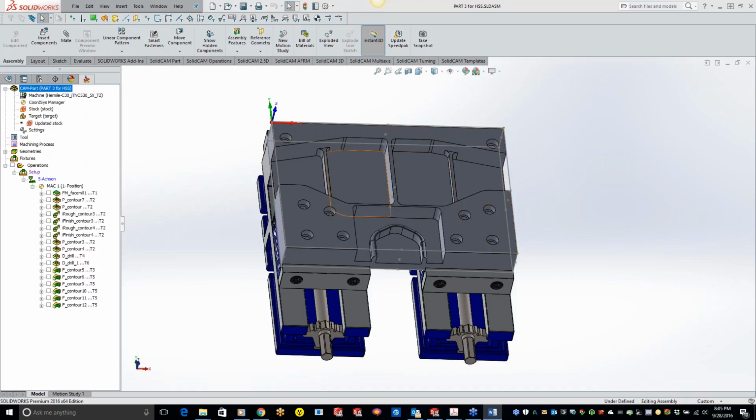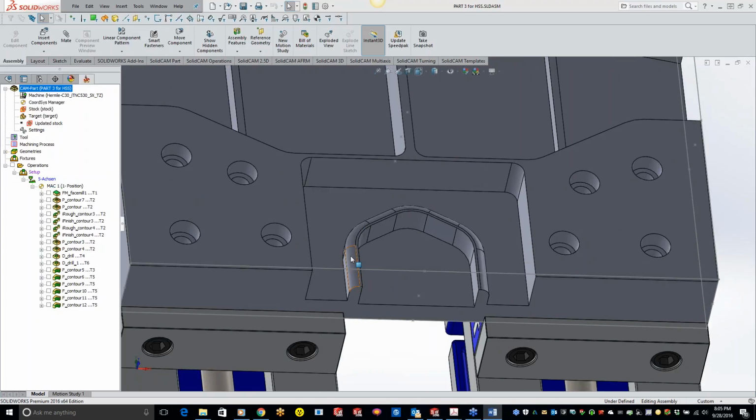So you'll see we have a 2.5D part. I've already programmed everything in here with the vises, fixtures, and all that stuff. If you have questions about the fixturing or anything like that, just let me know, and I can point you towards one of the other videos we did. But what we're actually going to be focusing on is this 3D surface coming around here. Now, granted, if you had a radius cutter, we could definitely do this with the radius cutter and just use a profile, but it's an oddball size. So either A, we'd have to get a custom ground one, which is expensive, or B, we can come at it with a 3D milling path.